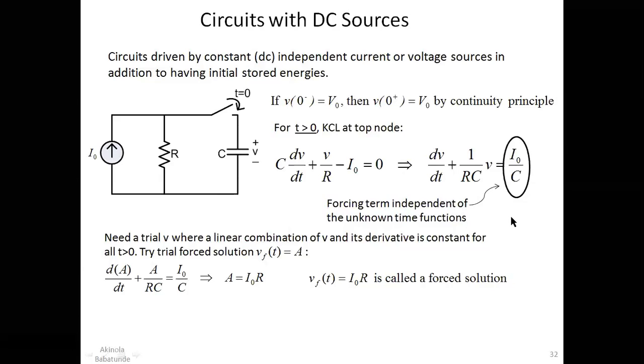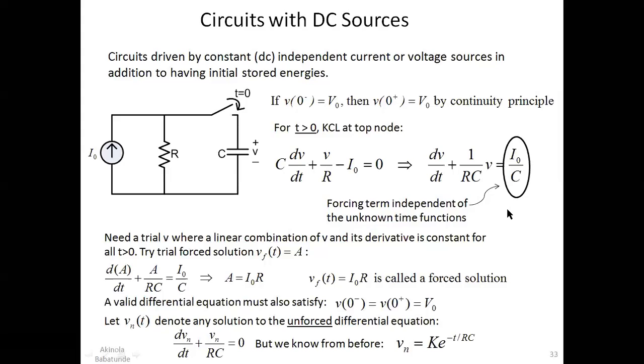All right. So if you want to do that, that simply means at that particular point, you can equate dV/dt plus 1 over RC V to 0. This time around, you can replace your natural response, which is V, and say your natural response is equal to Vn. So whenever you see V, you just put Vn there to denote that you're talking about a natural response. All right. And a natural response automatically helps us to get our characteristic equation. So in that particular case, this is going to be equal to 0 for a natural response.